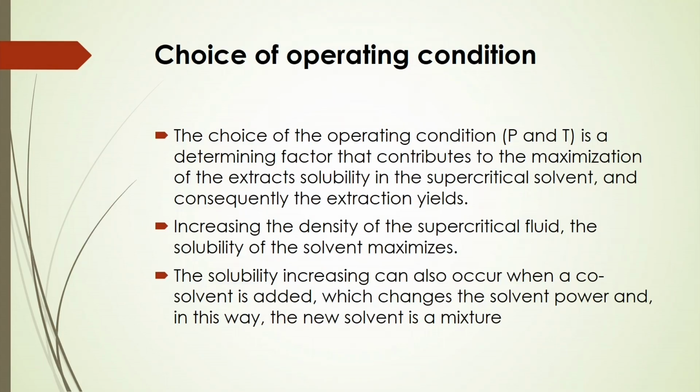If you increase the density, you will see that the solubility in the supercritical fluid will be maximized. Solubility can also increase when a co-solvent is added, which changes the solvent power, and this way the new solvent mixture will act to enhance the separation efficiency.